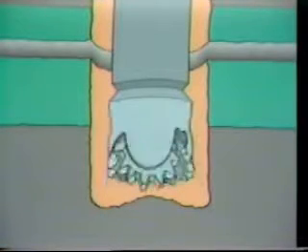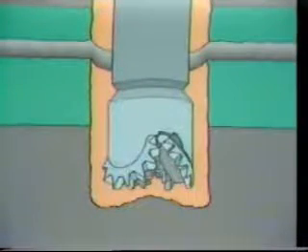lost circulation can occur, and the fluid pumped down into the drill pipe disappears into the rock formation, decreasing the amount of mud in the hole and setting the stage for a kick or even a blowout. In such situations, lost circulation material must be added to the drilling fluid to enhance its filter cake forming ability and stop the loss of mud.